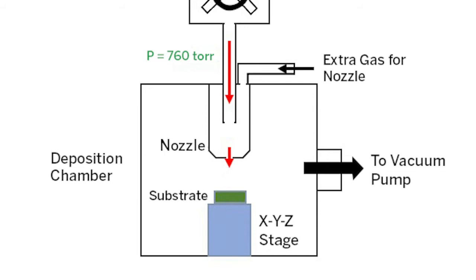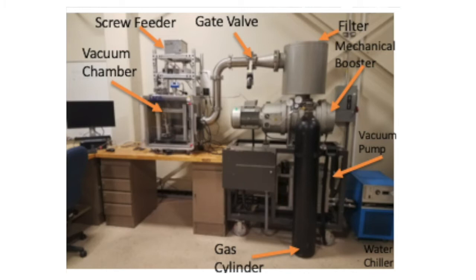the particles. And our typical particle velocities when the particles come out of the nozzle are anywhere from a few hundred meters a second up to about 1,400 meters a second. And we can control that by controlling the nozzle geometry, the gas type, and the gas temperature. When the particles impact at these kinds of velocities, they're moving fast enough that they actually plastically deform where they hit the substrate and they stick, and we build up a film. And we do this all at room temperature. And so we can actually directly write at room temperature metals and ceramics into patterned thick films.